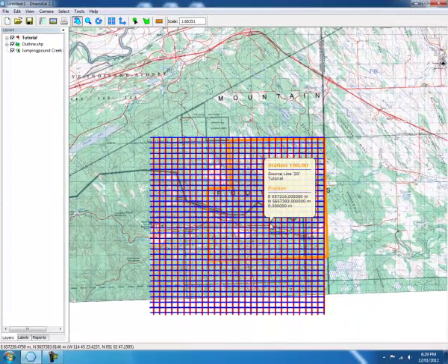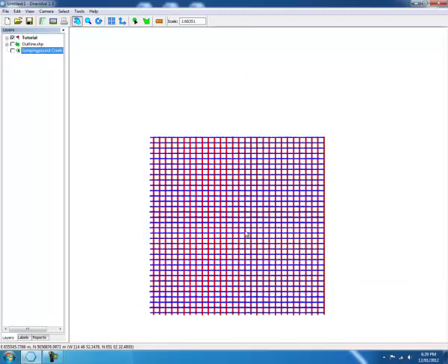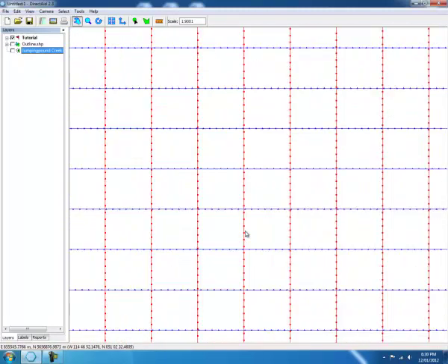When we built this project, we used a triple stagger design. I'll take a moment now to explain what that is. If we look closely at a few lines, we can see that the stations shift forward a little bit from one line to the next. In this case, the pattern repeats every 3 lines, hence triple stagger. What this does is to create a 3 by 3 midpoint pattern in the subsurface. This pattern can improve migration of recorded data and can also give us options for rebinning of the data after recording.